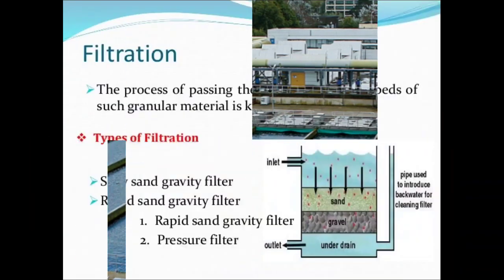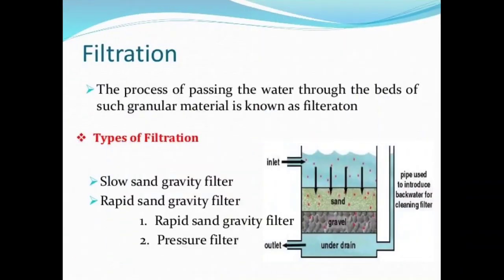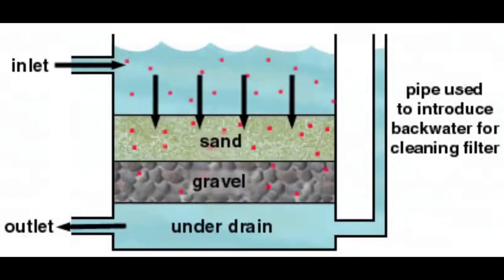The filtration process removes particles that are present in the suspension state. Removal takes place by a number of mechanisms that include straining, flocculation, sedimentation, and surface capture. These filters can be categorized by main capture methods. According to their capture capacity, they are divided into slow sand filters or rapid sand filters. Or we can provide screens.